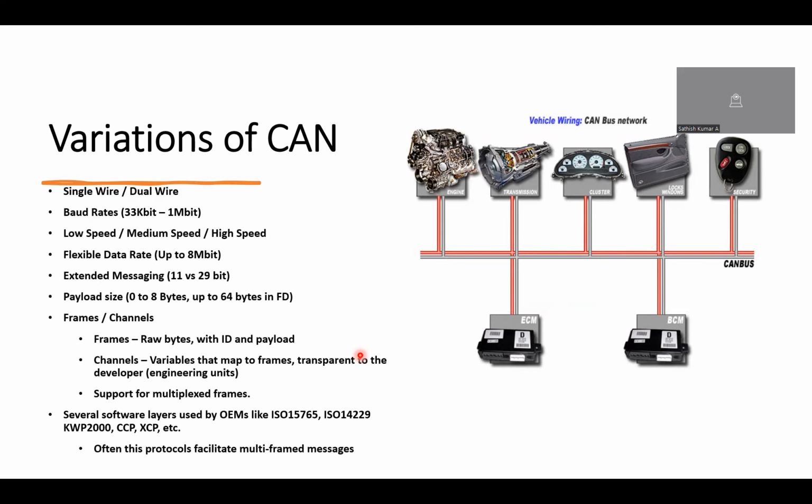Each channel will have the starting bit and bit length, as well as the conversion factor, basically the offset as well as the scaling factor. Based on this only we can find the engineering unit, I mean the real value, the actual temperature. So this information can be used for the conversion from the hexadecimal of the payload.